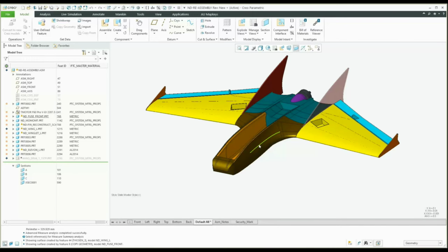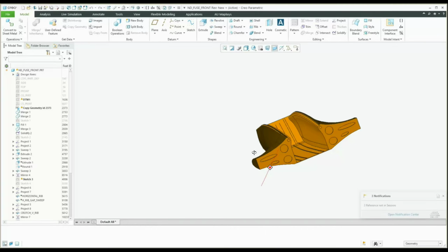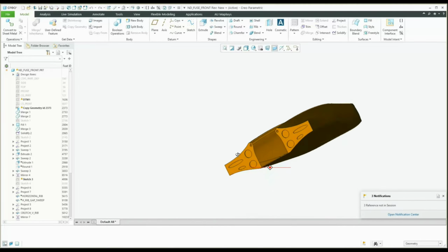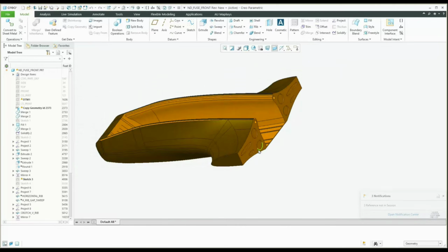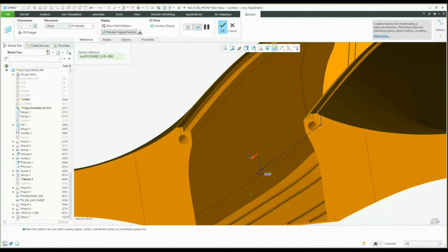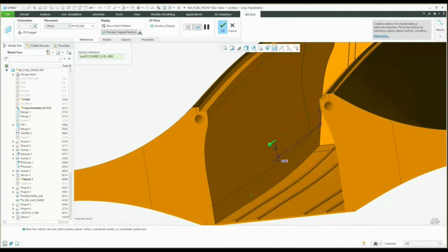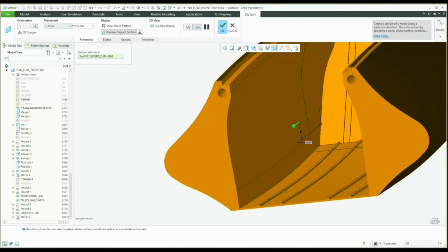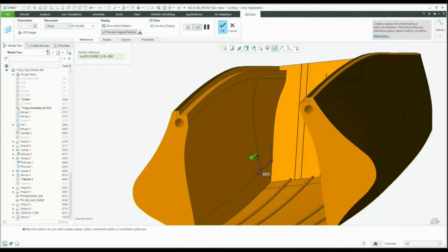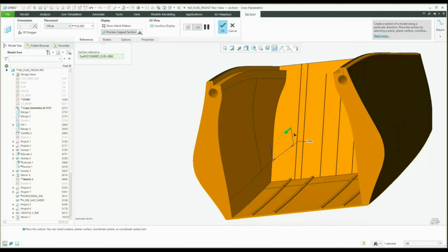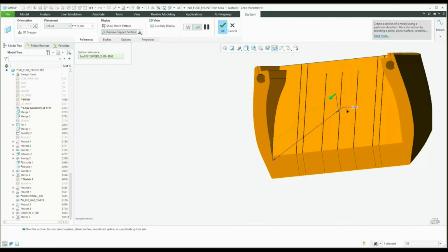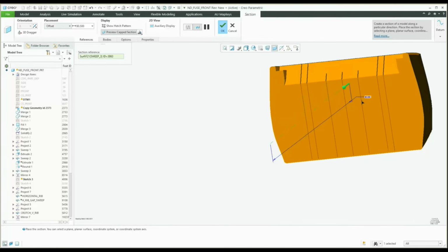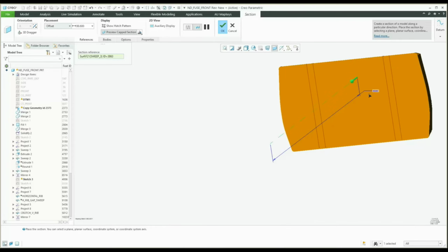I constructed the fuselage parts in a similar way to the wings, starting by grafting in the surfaces from the unibody aero part, and then adding detail to the models to be able to print in spiral vase. I experimented with modeling the fuselage parts as pure solids, which was different from how I did the wings. Even though the part is modeled as solid, you can still command the printer to look at the outer wall of the model and follow that as its spiral vase path. This can definitely make adding the internal features simpler than using surfaces.